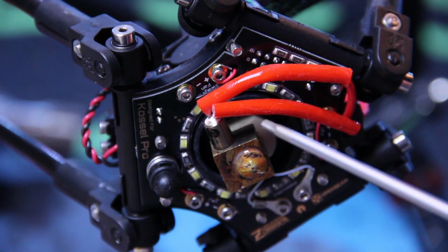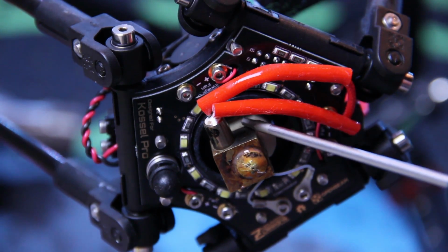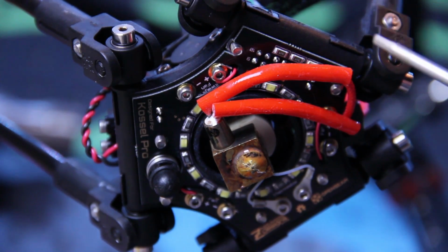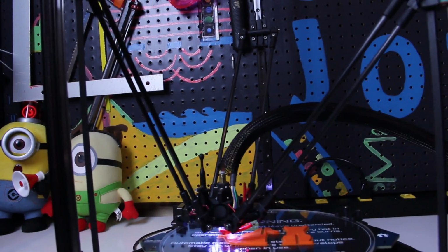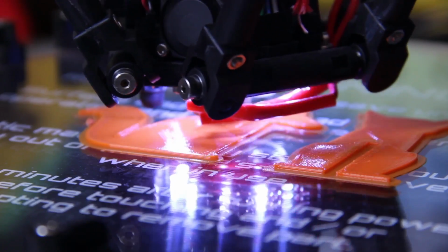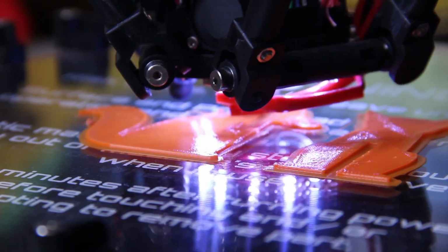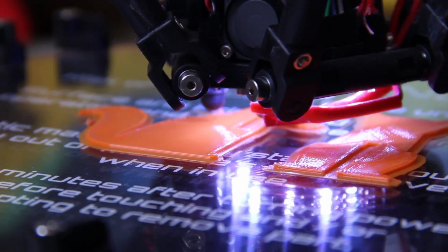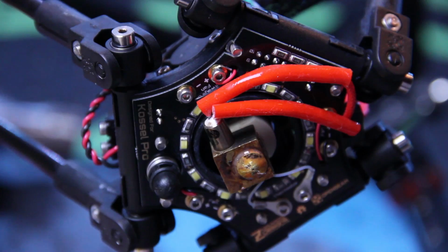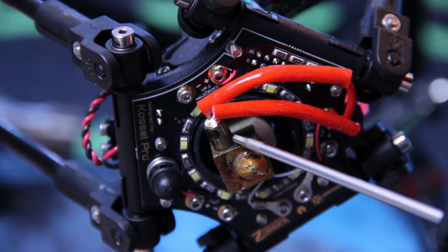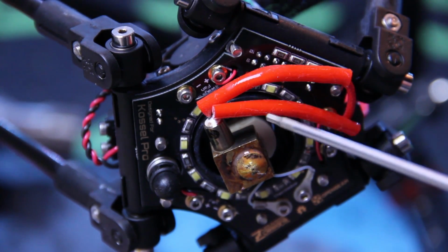And inside this nozzle, they happen to have a few fans to add cooling to this insulator that is inside here, and also to the part below. So those fans to the part below, that cools it so you can add the next layer? It helps the layer set well, so it can add more plastic. If it's too molten, you can't make a good solid, but if it's a little molten, it's actually good, because then the layer that's being melted on top can have a better bond with the one below. Now you'll notice on here also, this is where the heater is. This cylinder is actually a heater element, and these are its power sources.